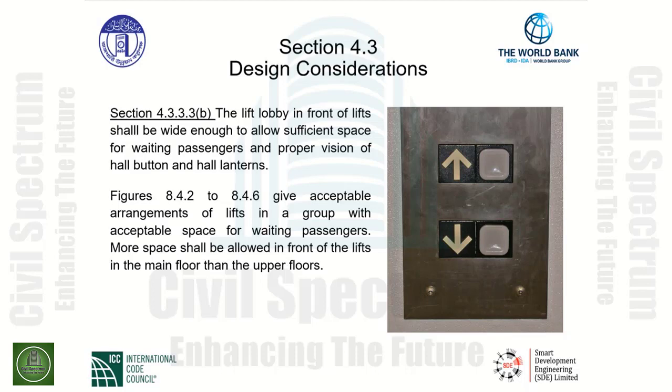Section 4.3.3.3, item B, the lift lobby in front of lifts shall be wide enough to allow sufficient space for waiting passengers and proper vision of the hall call button and the hall lanterns. Figures 8.4.2 to 8.4.6 give acceptable arrangements of lifts in a group with acceptable space for waiting passengers.